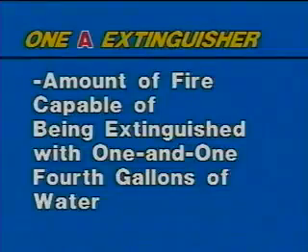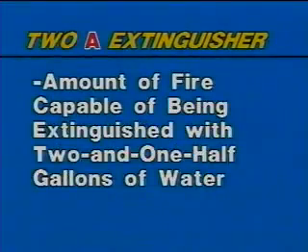A number rating of 1A is the amount of fire that can be extinguished with 1 1/4 gallons of water. An extinguisher with a rating of 2A contains 2.5 gallons of water and is capable of putting out a fire twice the size of a 1A extinguisher.